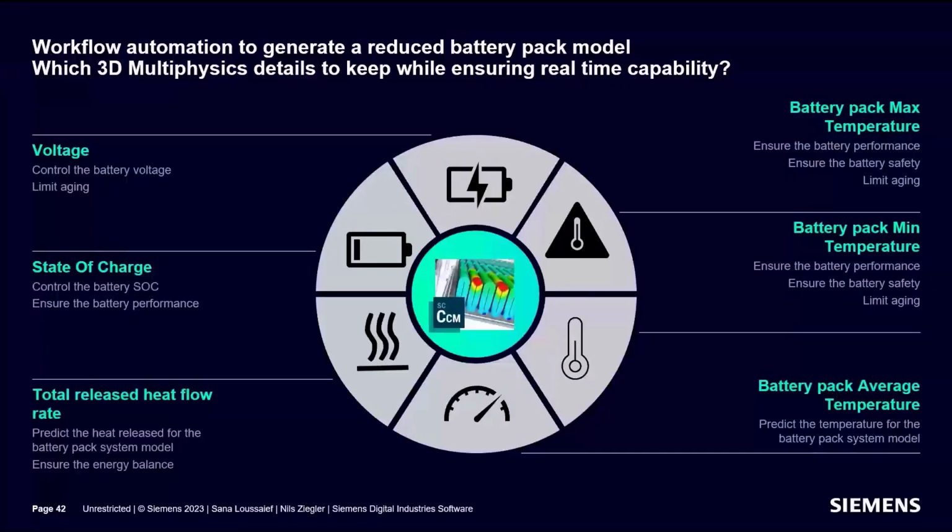Also, at low temperatures, we see slower diffusion and intercalation with the possibility of lithium plating. This is an issue since lithium plating removes lithium from the active cell, so it reduces the cell capacity. On top of that, lithium plating can cause electrical shocks.